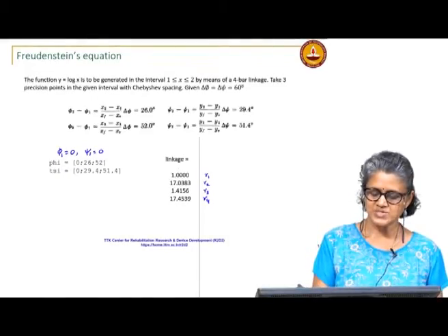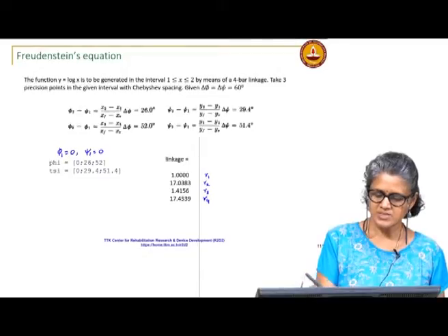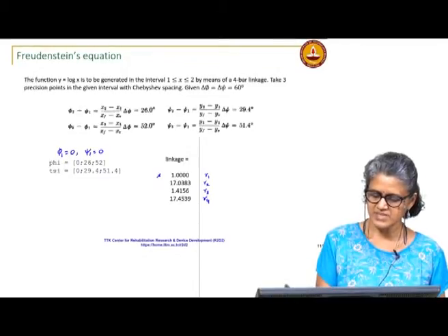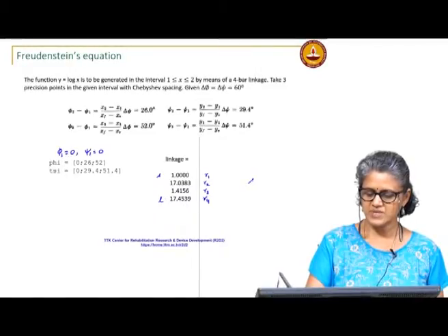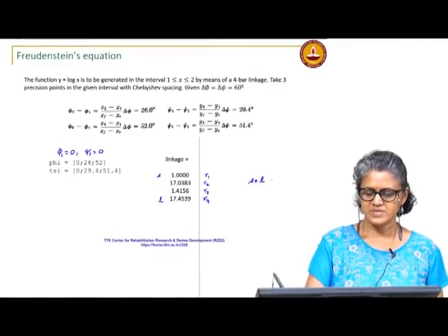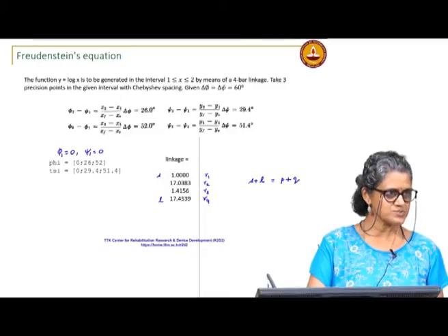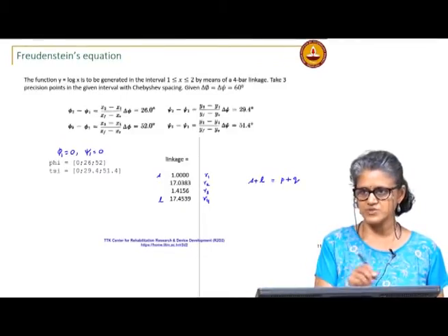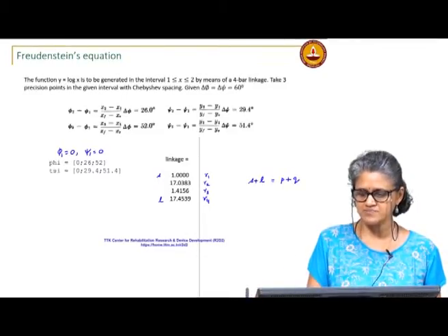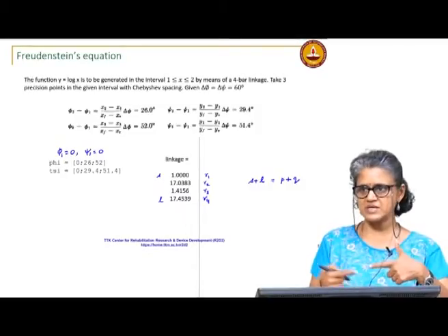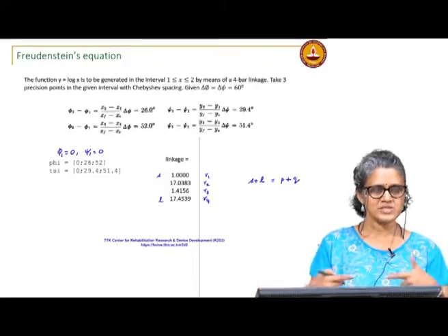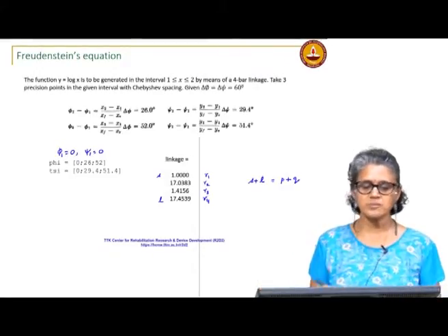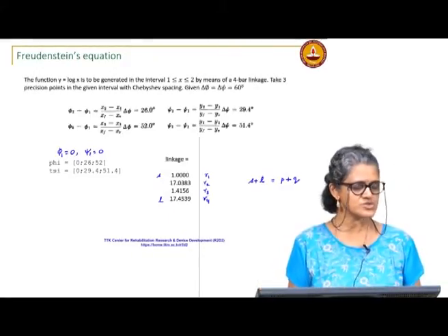You can also see, this is the smallest link S, L, S plus L is equal to P plus Q. So, you get the change point, you get a Grashof neutral linkage because you chose phi 1 equal to 0, psi 1 equal to 0, the first precision point, right, you get a change point there. So, this is probably not a desirable solution.